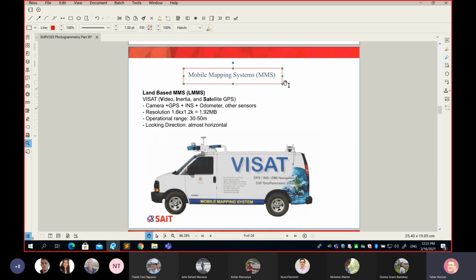Now, this was a dream. What you see on my screen here was a dream for every surveyor. Surveying was done for years and years using a static technique. You guys remember first year surveying? How did you make a map for one area? I need to remind you. You pick points on the area called the traverse. You fix them on site. This creates a kind of framework of coordinates. You measure distances and angles, and at the end of the exercise, you know their X, Y, Z.